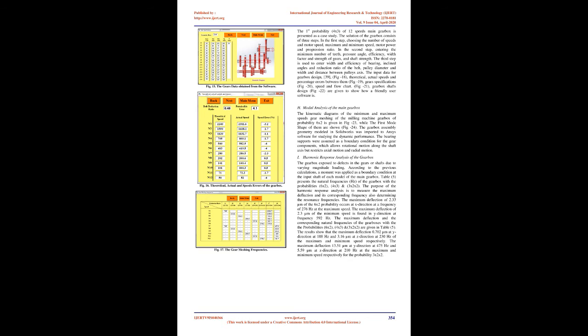In machine tools, speed regulation is achieved by more than one method using different progressions such as geometric, harmonic, logarithmic, and differential progression. The best method to reach the proximity of speed is the differential progression. However, as an international standard, geometric progression is widely used in machine tools. Speeds are valued as the following in geometric progression: first speed, second speed, third speed. The general formula for calculating speed is n_z = n·r^(z-1), where z is the speed number, n is the motor speed and r is the geometric progression base.